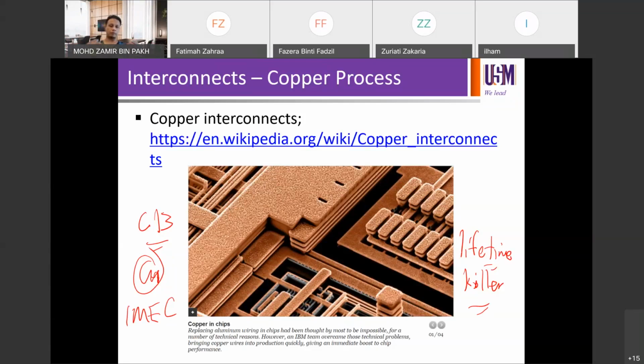lots. And copper lots or copper wafers were placed in the green pod that the operator carries, which is green in color. The code that we use is green color. Green means copper, right? And other pods, the white pod, the transparent pod, are for non-copper process. So you're not supposed to have green pods and transparent pods running at the same time, because the copper in the green pods, in the green wafers, is going to contaminate your non-copper lots.